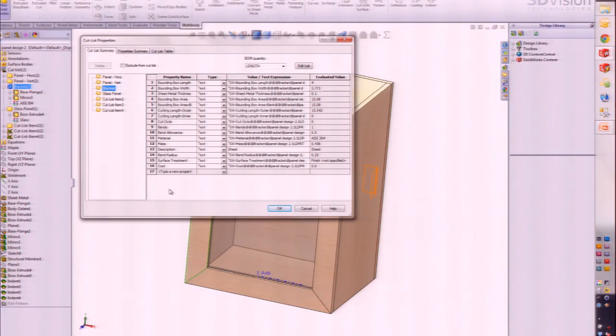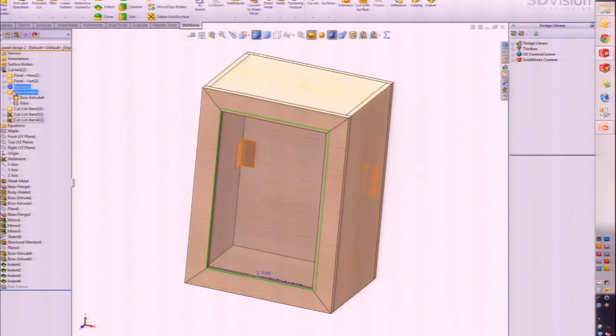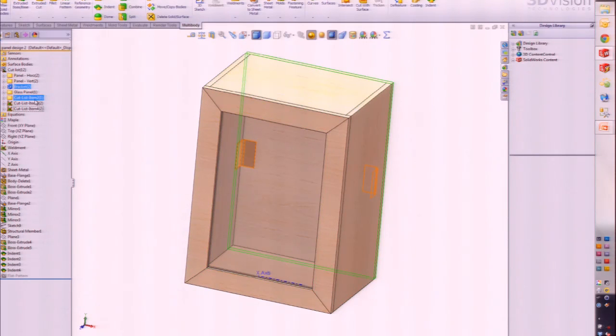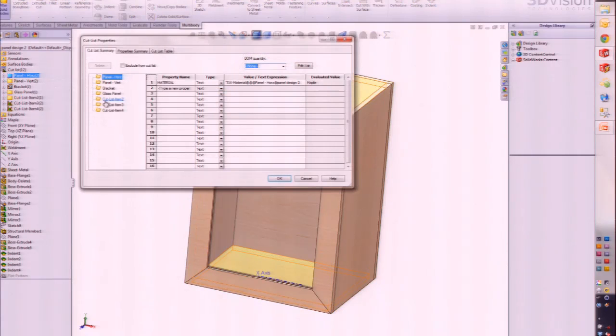This stuff is what makes SolidWorks costing possible. It finds out the overall cutting length around the perimeter, the inside cuts. You could track the overall linear length and your laser cutting speed and figure out a total time for cutting that blank of the sheet metal part out on your laser cutter. All kinds of information. The problem is these little manila folders were just extrusions, regular features. I right-click on one and hit Properties, and bummer, there's nothing. There's a material, that's nice, but nothing else, right?